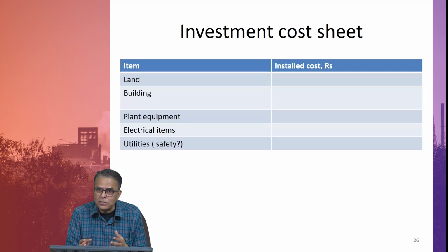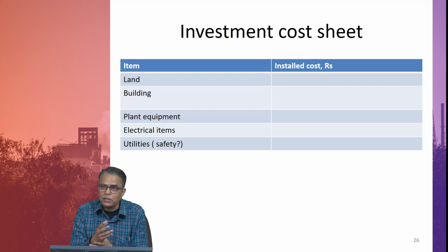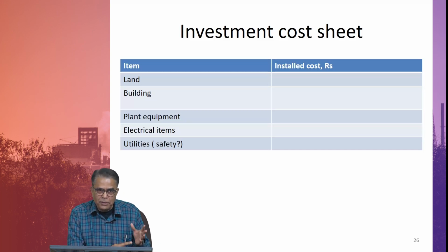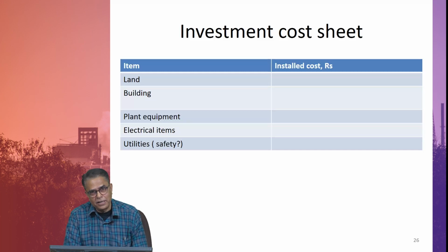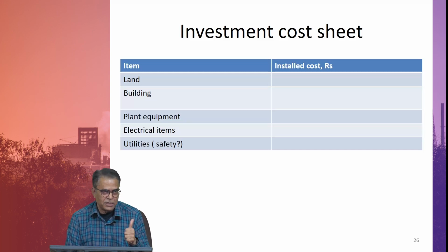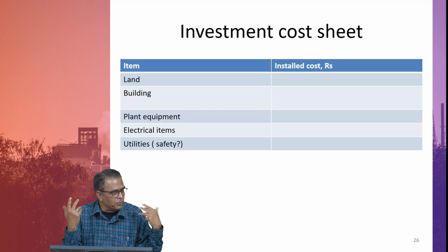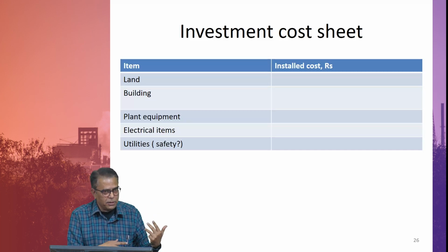What happens to these anions and cations, by the way? Water comes out pure, but after some time you will backwash those resins in order to regenerate them. So, you will generate some effluent and that effluent can't be just let out. So, you will have to probably treat it. This has to be captured in the process flow diagram and in your engineering calculations. Just as an example, all the vessels whatever you do will have a vent, through the vent some organic vapors will be going out. So, you will have to have a vent VOC control incorporated.